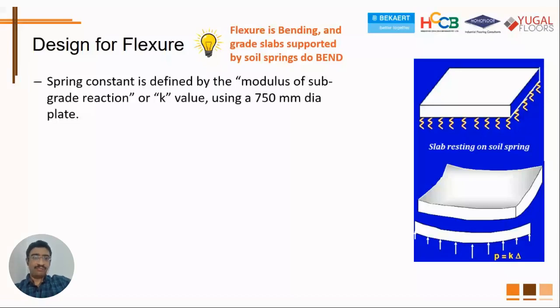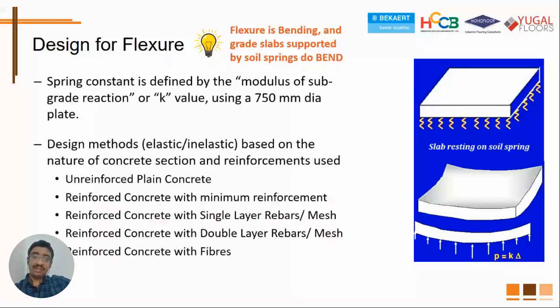Now, typically, you are placing the slab on a set of springs which has a notional spring constant or K value. And the design methods, this is all given in the guideline. The design methods, whether elastic or inelastic, are based on the nature of the concrete section and reinforcements used.